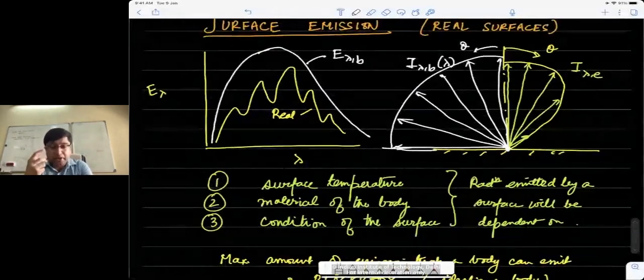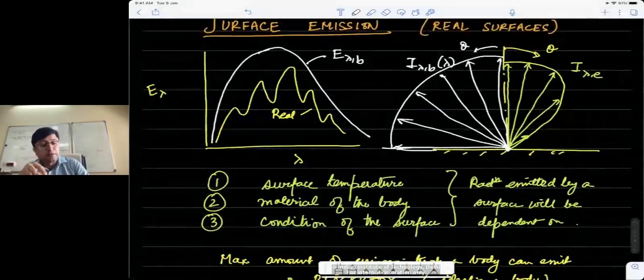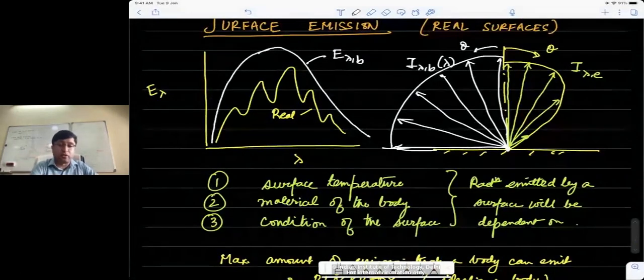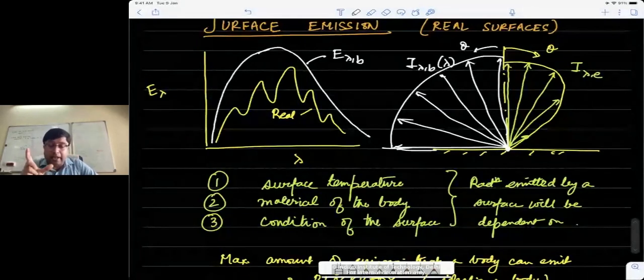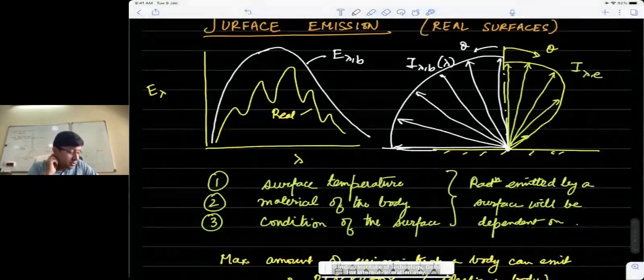Simple reason: what you're perceiving as a black surface is actually in a very narrow spectrum, the spectrum that corresponds to visible radiation, which is about 0.4 to 0.7, or 0.75 microns. So it's a very narrow band of the entire spectrum. And so something that appears black in that spectrum may not be black in the other wavelengths that our human eye cannot perceive, or we don't have the sensory perception to make out whether it's actually really black or not.